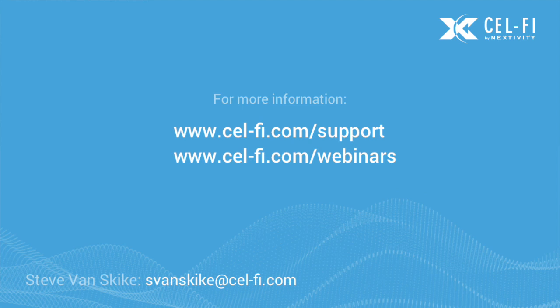The main thing I'm looking for is things like, maybe I've got 15 megabits per second down, but 20 kilobits on the uplink. Something is happening terribly on the uplink at that base station. Or maybe I'm seeing really low data rates on the downlink, so there's pilot pollution hitting the donor antenna. I need to move it or choose a different antenna. So it's the trend that I'm really looking for, not the absolute values.